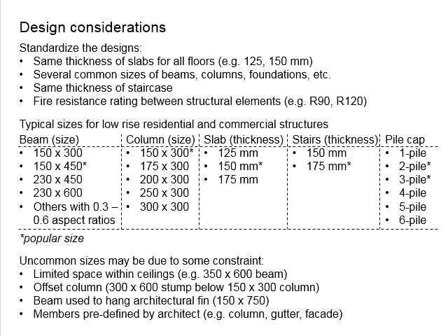Another one: when the ratio between the width and the height of the column is extremely large, 4 reinforcement bars at the corners might not be sufficient. Let's say now your length here is 400. Most likely you need another 2 longitudinal reinforcement bars to control the cracking on the longer surface of the column. Of course, the other sizes are also applicable.